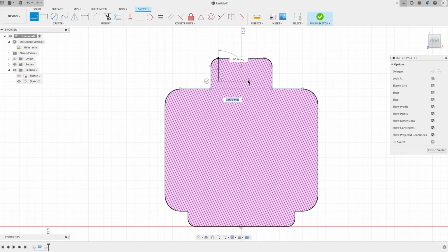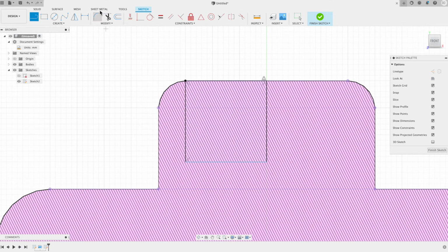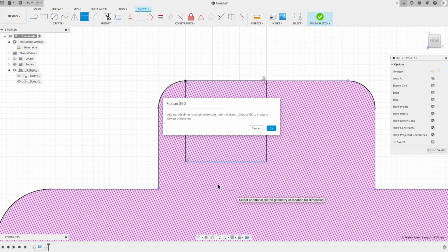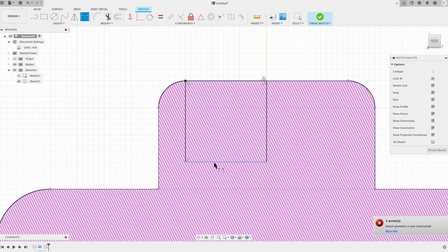But before that, I click on in the sketch palette slice graphics, which is what I want to do. Then I project some geometry at the top, and then I draw a rectangle or just 4 lines halfway through that cylindrical shape that we have at the top.